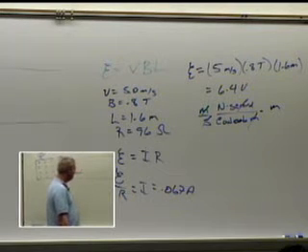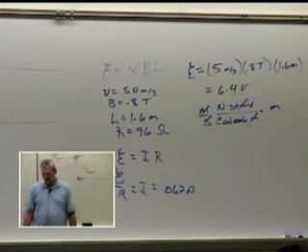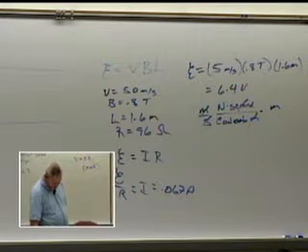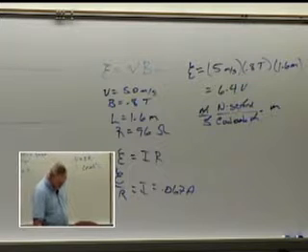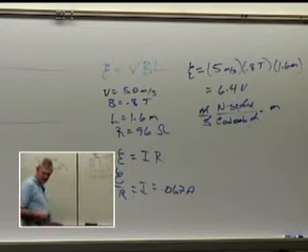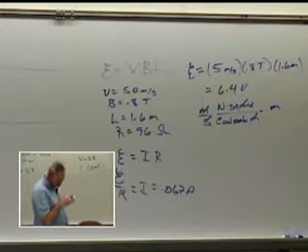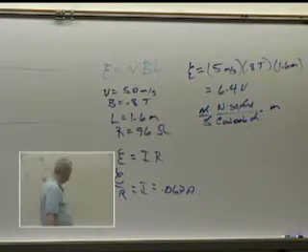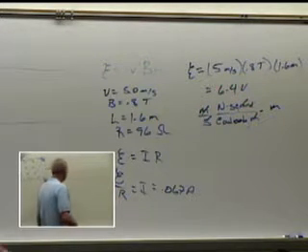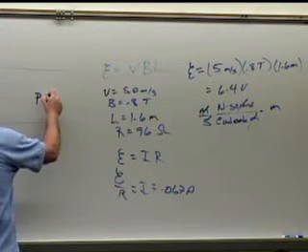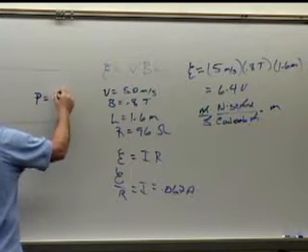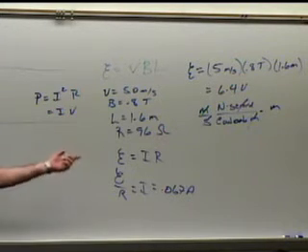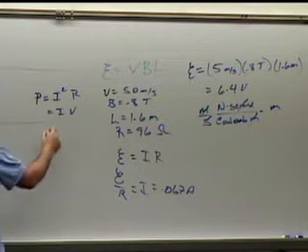Let's find the power. What is the power? Did they give us time? Oh, we don't need no stinking time. We can figure this out. Well, they do say for 60 seconds. Power, watts. Power is what? Yeah, I squared R. I wasn't going for that one. I was going more for IV. Same thing. Or V squared over R. Any of them will work. But we've got all of them.